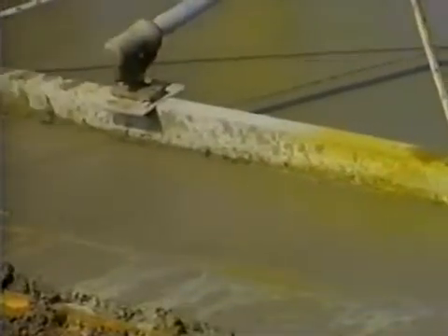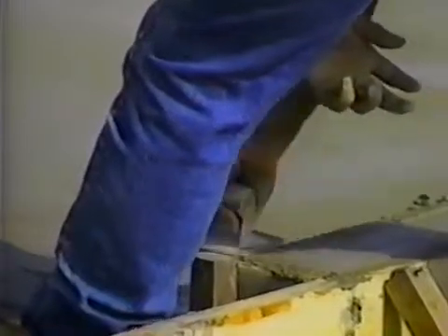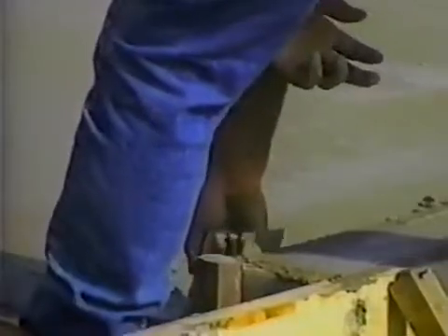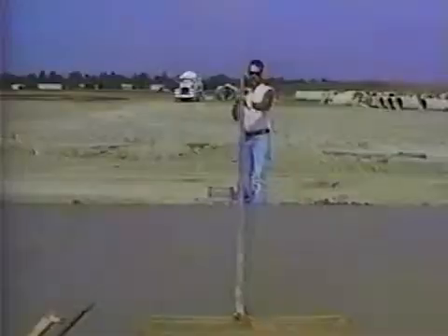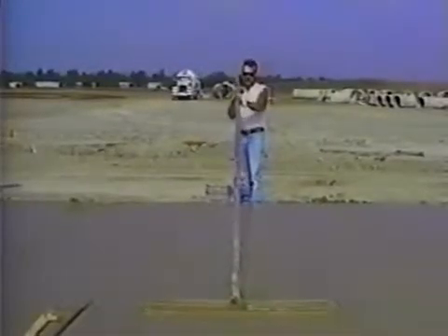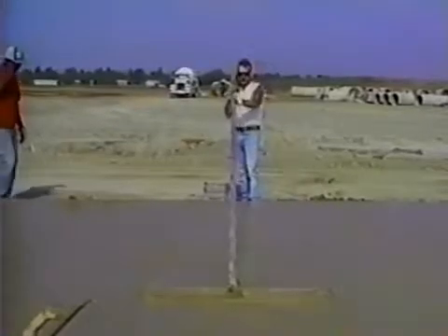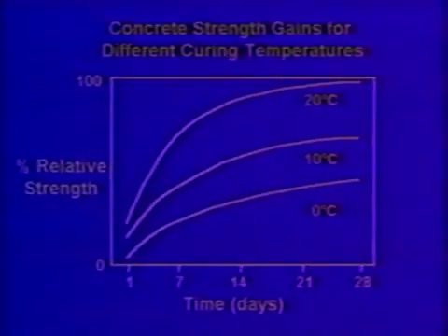The rate of hydration can be controlled several ways. Factors such as temperature, cement type, and admixtures influence the rate. One of the most important variables is the ambient temperature. High temperatures speed up hydration so that setting is faster, as well as subsequent strength development. The opposite occurs when the temperature is lowered.